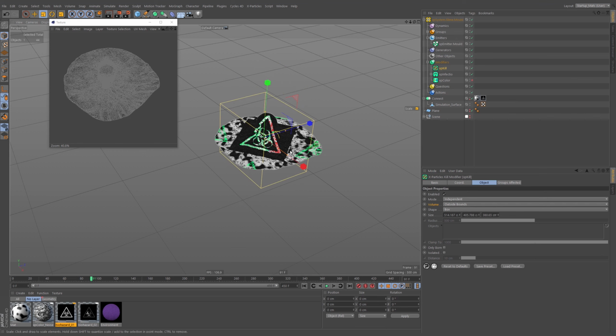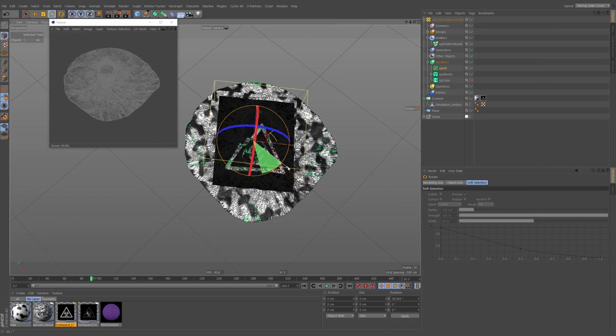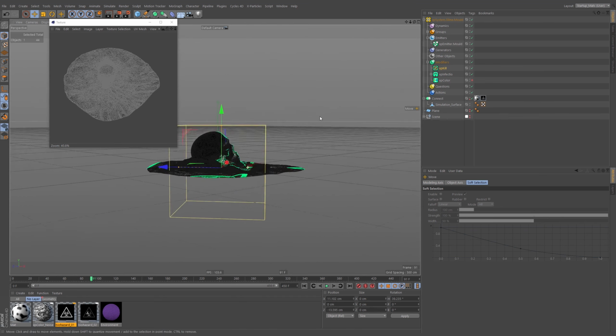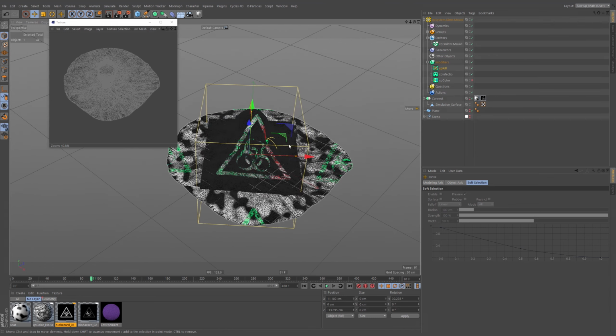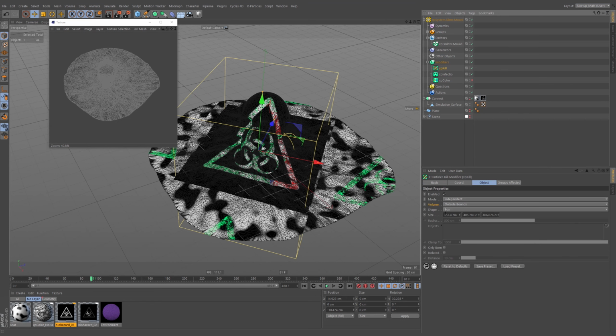And if I pull this down here, you can see that. Now I could use some geometry as well if we wanted it to be much more accurate. But since it's a texture that's causing this, I can just do that. Now, say we ever had particles that were going to move outside of this box, and we only wanted it to stop them from emitting at the very first frame, you can actually set that in the kill modifier to only born. So it'll only operate on the born particles.